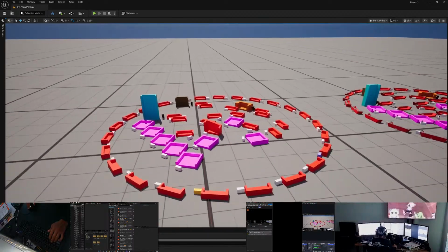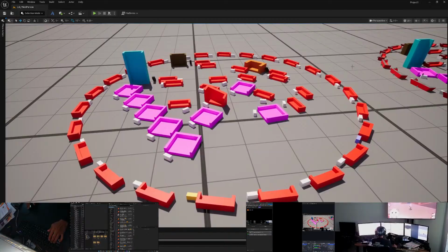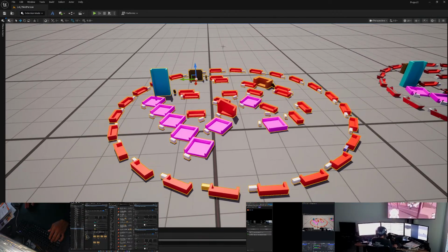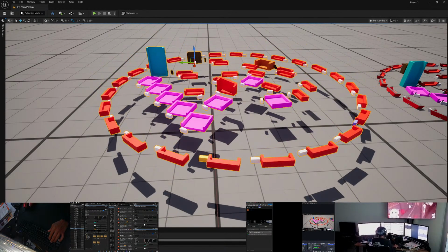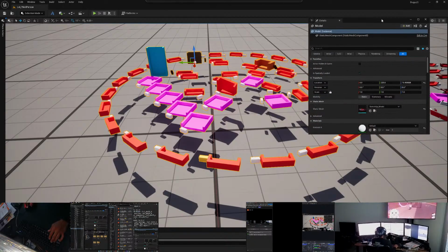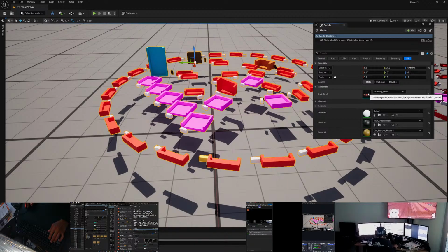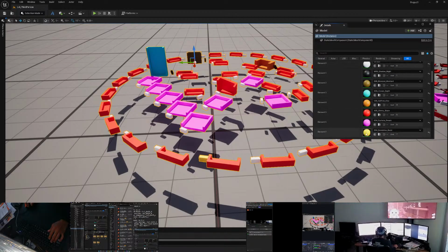And then anything that can live as one entire static mesh, even if it's multiple assets, you can combine meshes, assign a different material slot to each item or part of the mesh that you want to be a different color, and then that particular item will reflect in your details panel to have one static mesh and then a variety of material slots.